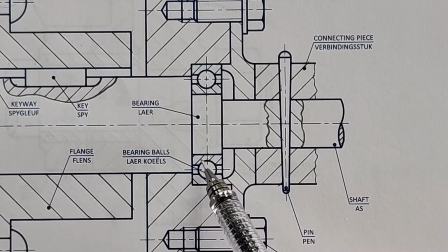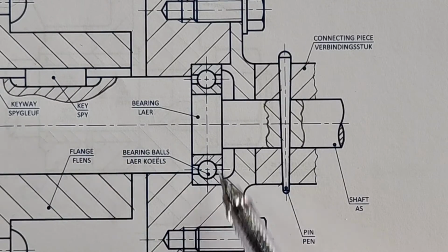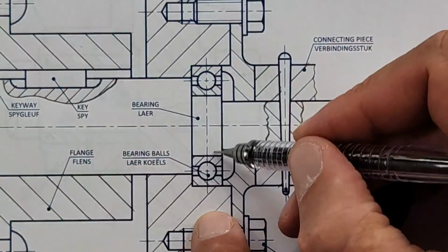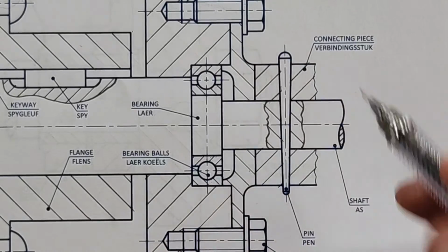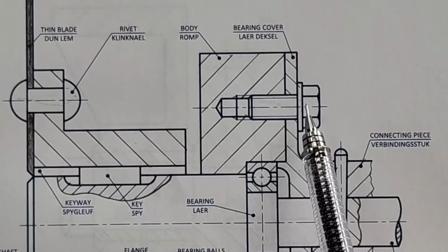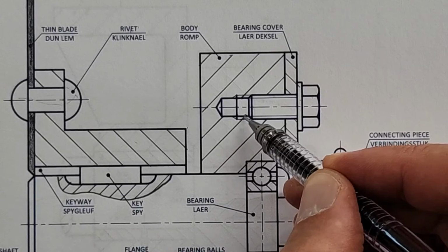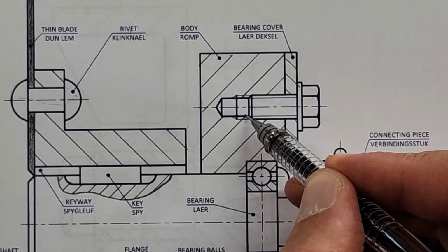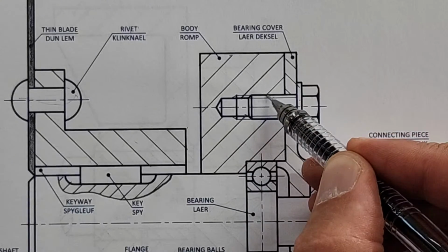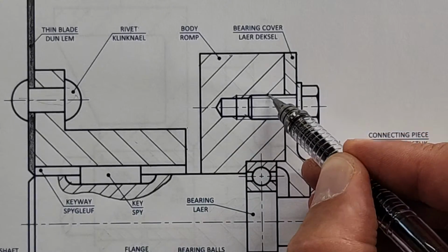Make sure that when you have a bearing, when it's two parts to it, the hatching direction changes. You don't hatch any fasteners. When you do have a screw thread and it's internal and there's nothing screwed into it, it goes all the way to the inside. When there's something screwed in, it stops.